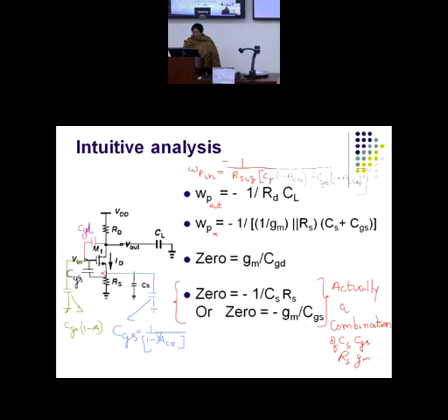Okay. And what would be the total capacitance at this node? It would be a component of CGD. Look very carefully. A component of CGD, a component of CGS. Okay? So that is what I am doing. I am getting the gain from Vin to Vout, and a gain from Vin to Vx. When you take the gain from Vin to Vx, it is a common drain amplifier. Clear? Input is gate, output is source, behaving like a common drain amplifier. I have to use that expression. And if you move from Vin to Vout, it is a common source amplifier.